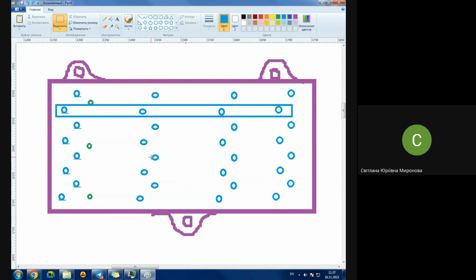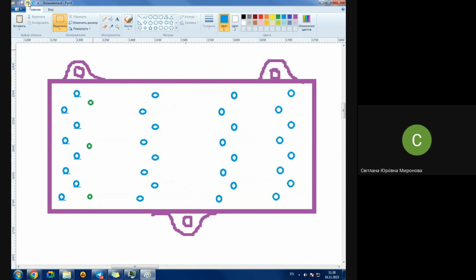It's so-called foolproofness. Usually, in case the structure is regular, assembly holes may be placed along row lines like a grid. If the structure is regular, if all the stringers are completely the same, and you occasionally mix up one stringer and another, nothing wrong happens in structural meaning.